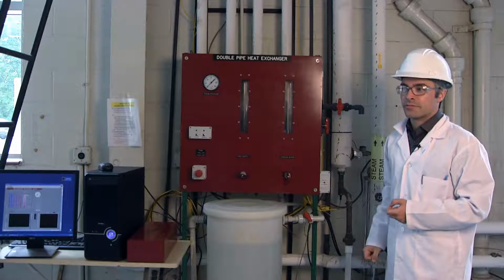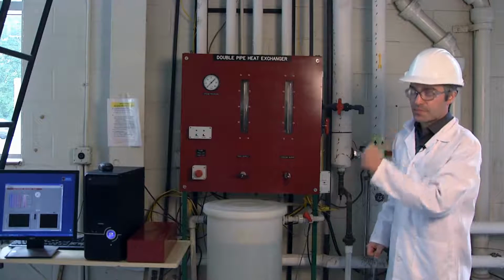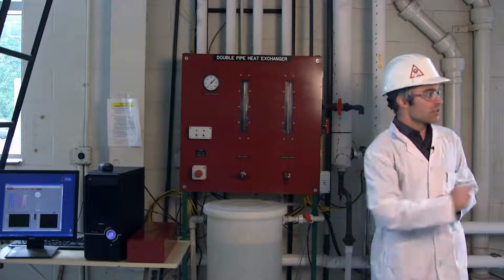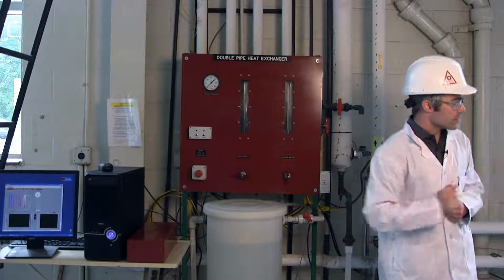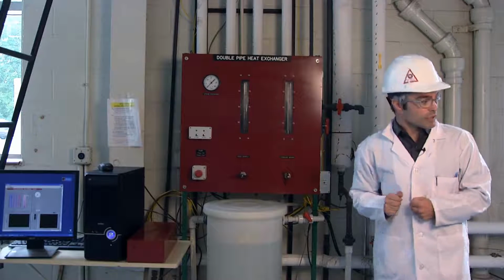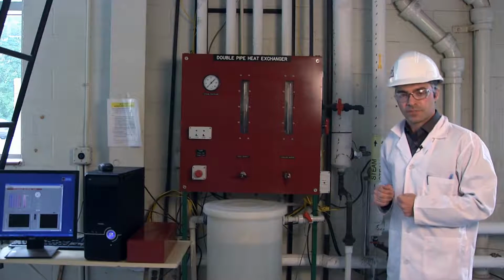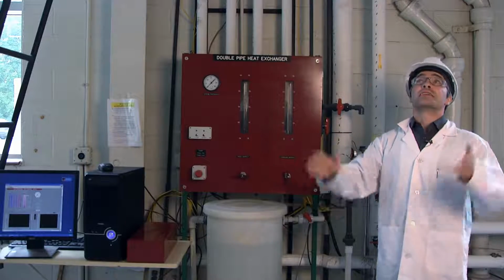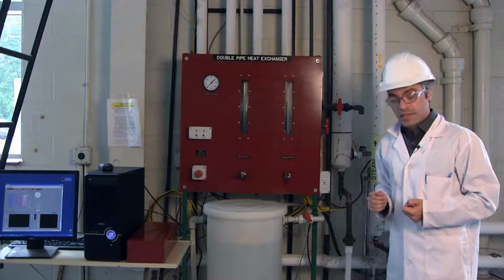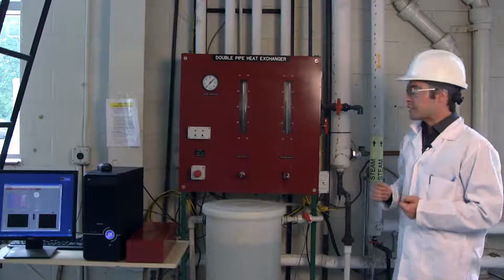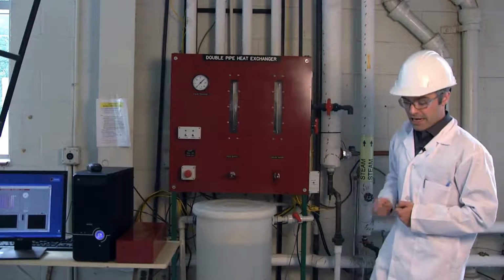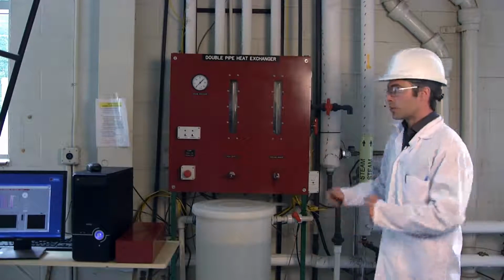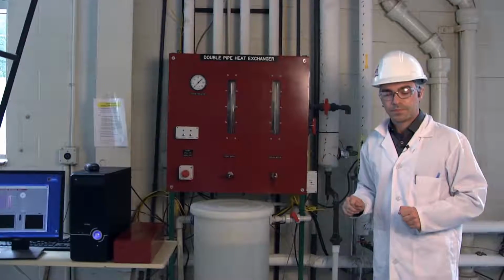To our left, we have the liquid-liquid extraction and distillation. Each would have their own safety considerations. And on the right, we have the evaporation unit and possibly the CO2 or SO2 gas liquid extraction. Each one of these carries their own concerns, and you must always be aware of your surroundings. We also will have students working above us. Therefore, whenever we're working in this laboratory and on this apparatus, it is a requirement that we have steel-toed boots, hard hat, safety glasses, and lab coat. Not only for this lab, but for working in the environment.